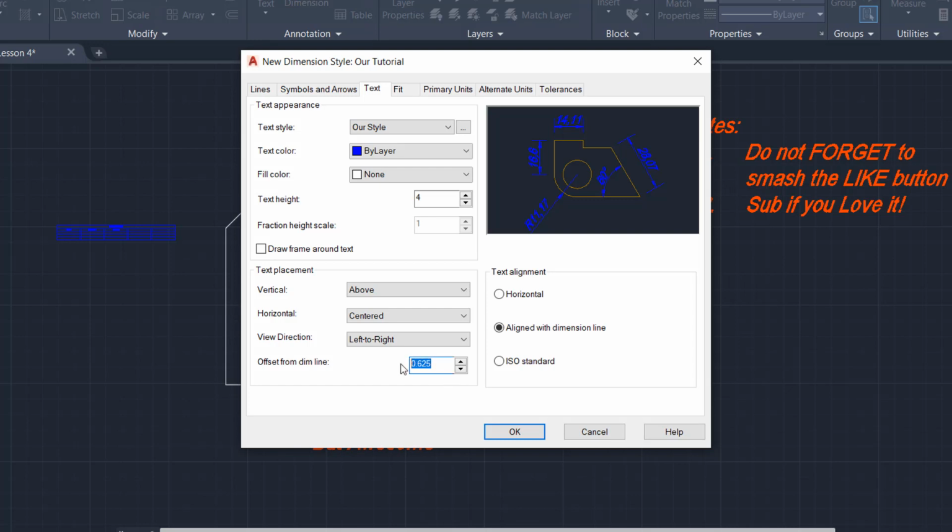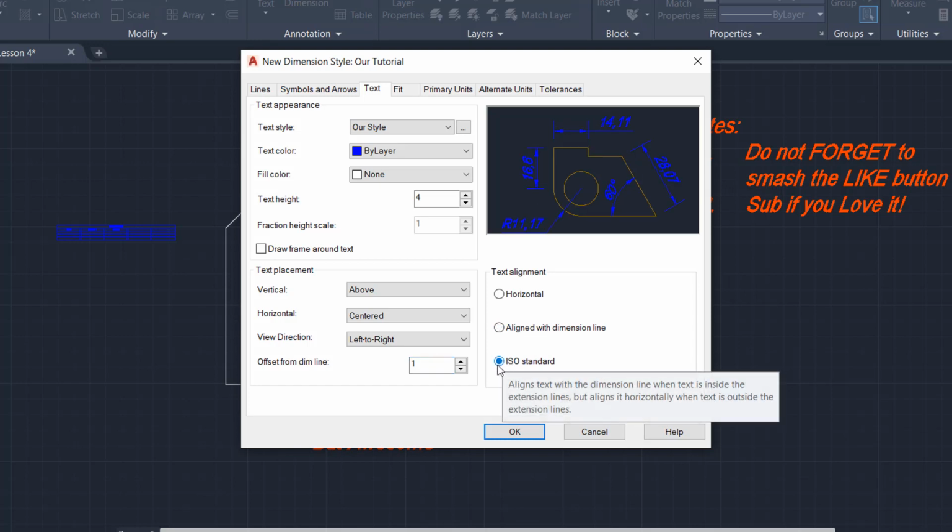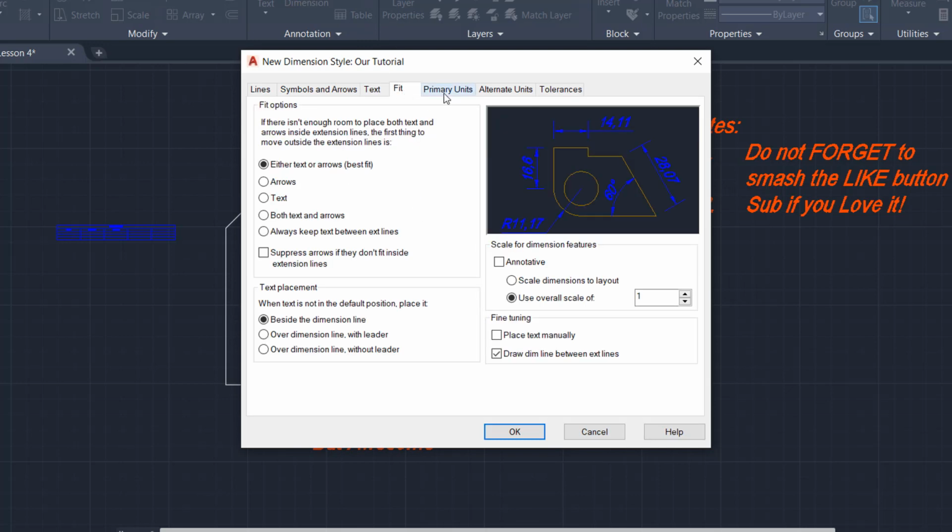Offset from dimension line, as name suggests, distance of the text from dimension line. Let's increase it to 1. Text alignment, experiment with them. I mostly choose ISO standard. It's a metric standard where anything that is radius or diameter related has a cranked dimension line. Fit tab, no need to change anything here.